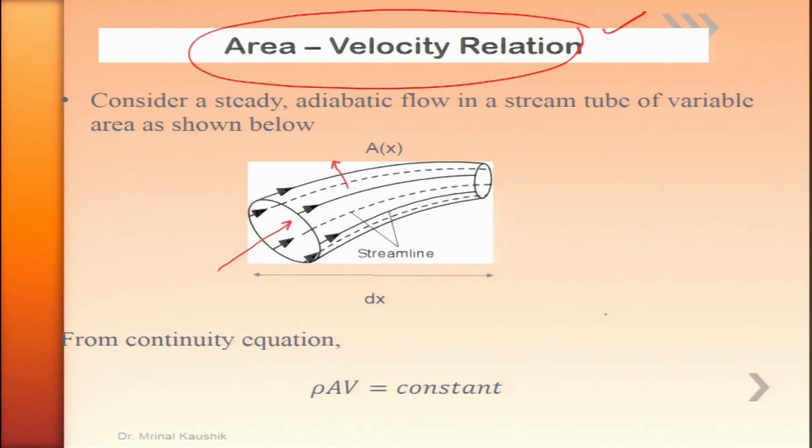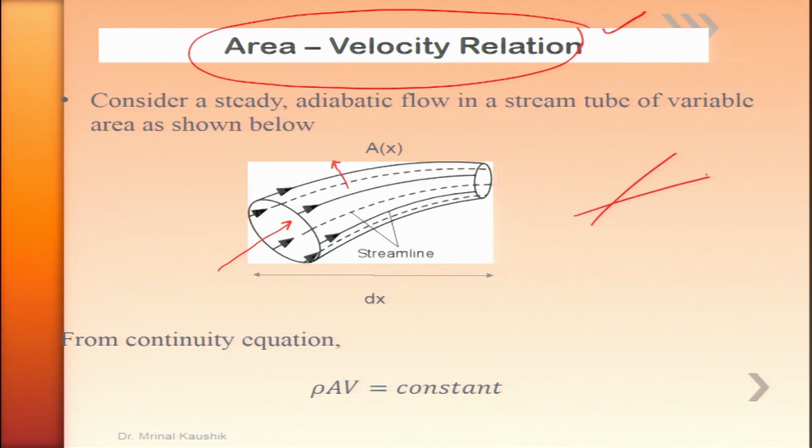When the streamlines surround a flow, a cross flow situation does not occur, because if the flow were allowed to cross a streamline, it would violate the definition of a streamline. At an intersection point, there would be 2 tangents, one on each streamline.